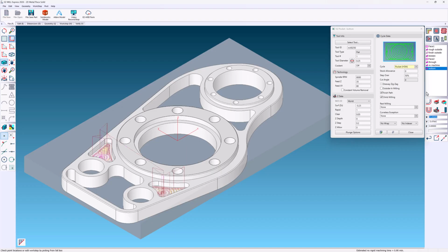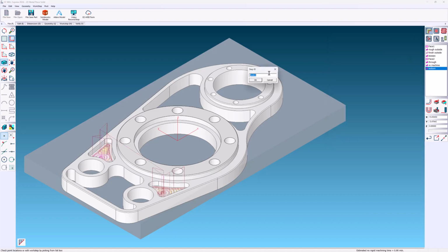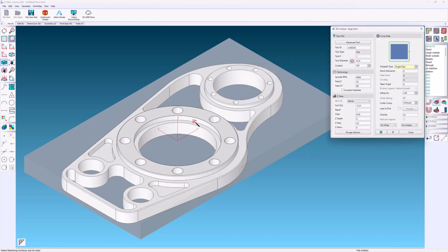Now for our contour. We may have selected the vertical surface for this feature, but EasyCam recognizes that it should not violate the surface below. We'll apply a multipass, adding stock to the wall of the contour, allowing us to take smaller steps as we creep up against the wall. I will share a tip. We can take the total stock and divide it by the number of passes we wish to take. This is possible because every dialog is a calculator.